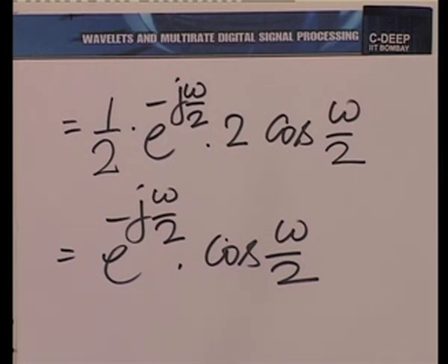Let us sketch the magnitude and the phase of this frequency response. Recall that for discrete systems, it is adequate to determine the magnitude and phase response in the region omega from minus pi to plus pi. We do not need to go outside that range, because the frequency response is periodic with a period of 2 pi. Whatever occurs between minus pi and pi is going to be repeated around every multiple of 2 pi.